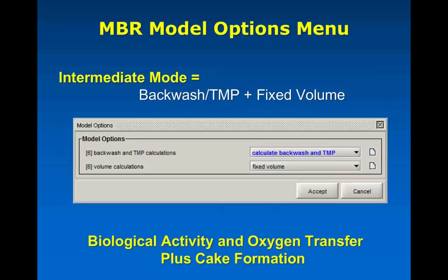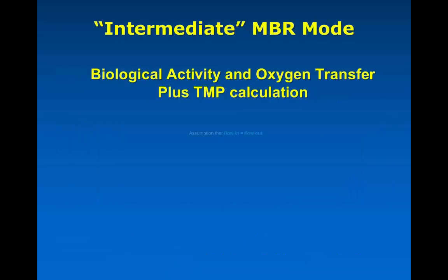By that, we want to do a mass balance of the solids that are captured going onto the cake, and then they get returned back to the liquid when things are backwashed or relaxed or scoured off by air, or just basically diffused back into the liquid, or detached back into the liquid. So this allows us to basically model everything that simple mode does, all that biological activity and oxygen transfer, plus actually take a look at how much pressure is required to run this particular system.